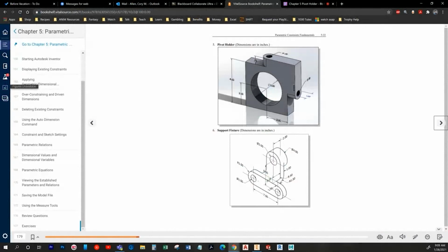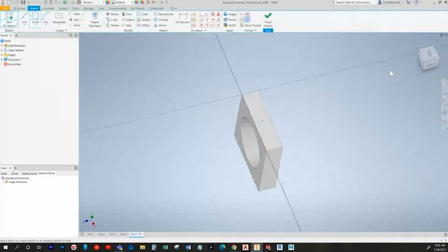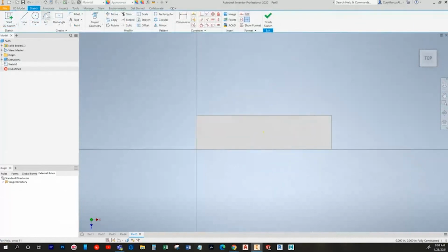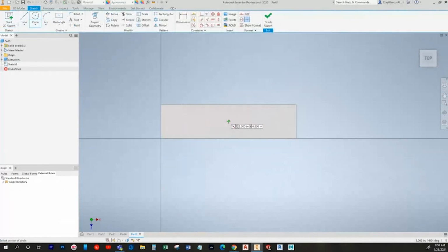So all that we're given is it's 0.75 extrusion, and then you're kind of left to assume that the center is aligned to the center of this part. So I'm just going to go ahead and draw the profile. And this is actually going to be the center of the part, so this kind of works out pretty well. Then I'm just going to go ahead and project some edges. And I was hoping we might get more info here, but it didn't quite grab it all. If you saw, it kind of implied there was a tangent, but it didn't snap to it, so that's okay.